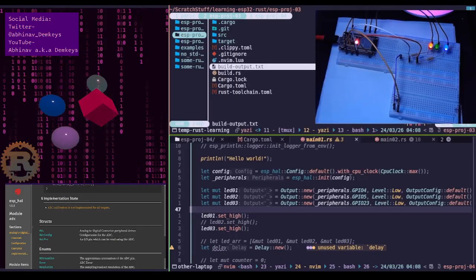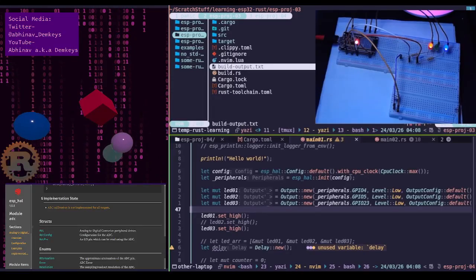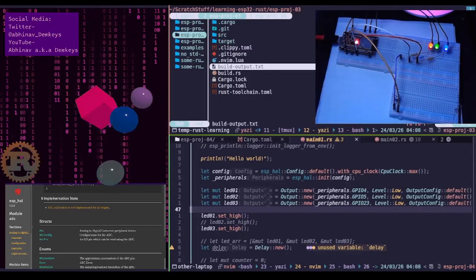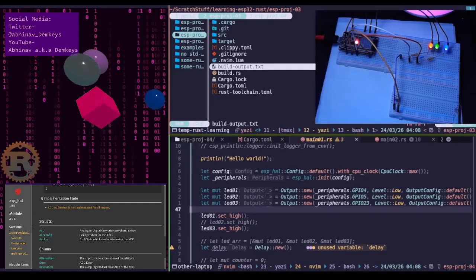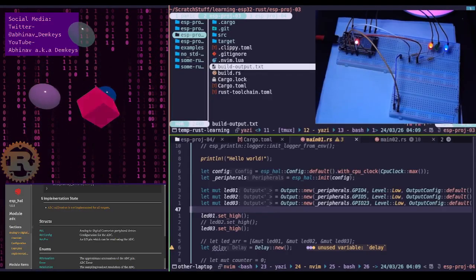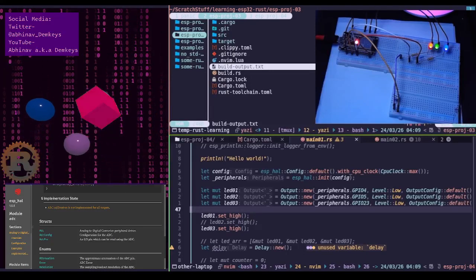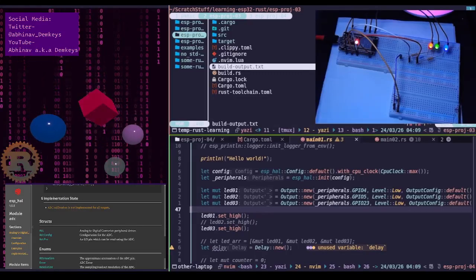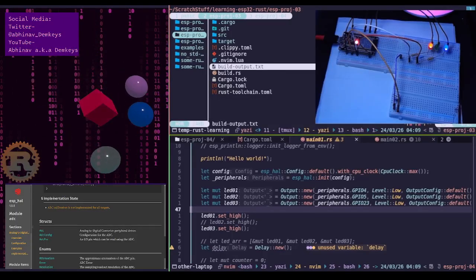Connect the pin of what? The multimeter? Okay, fine. Let's look at point B. Connect the pin to a known 1 volt source and then read the ADC, let's say 1242. Now that you have two coordinates, you should be able to calculate the slope and maybe the intercept as well. I think so. Now that you have two coordinates on a graph, you can calculate M and B to fix every future reading.